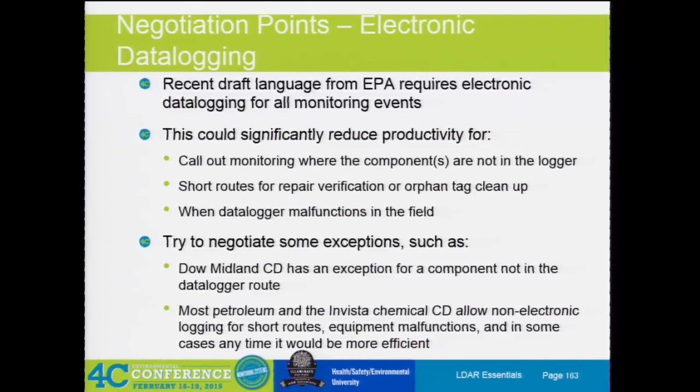I know California requires everything to be electronic. That's in just their state rules, right? That's what I thought. And I know that was an issue with California for a while because they have the tiered monitoring stuff. So they have a 100 within California, but it didn't trigger the CD, which was at 200 at some sites, and then the actual leak. So they were having anything above 100 to 200, which was their action level for the CD. They weren't recording those in the data logger so that it didn't think that it was an actual regulatory leak type thing. But I think it's since been fixed since I was at the facility that was having that problem. They would do all those on paper and then transpose them back into the database, which makes for a whole bunch of a mess.